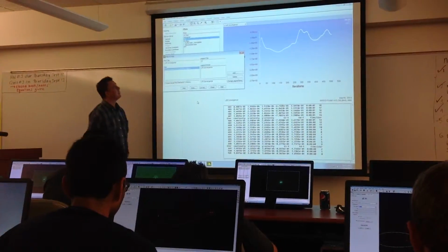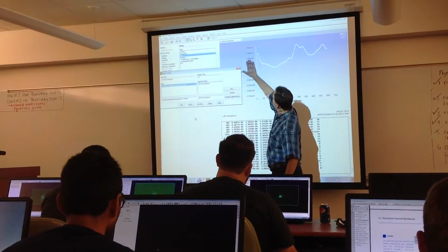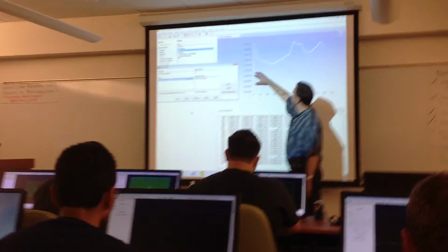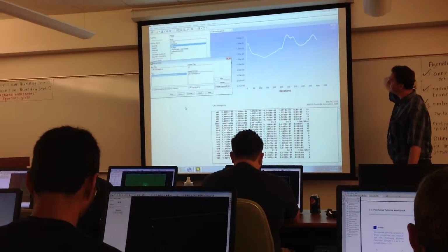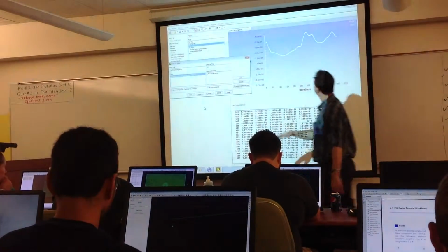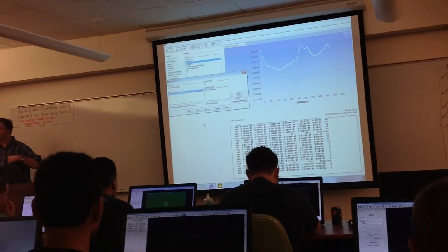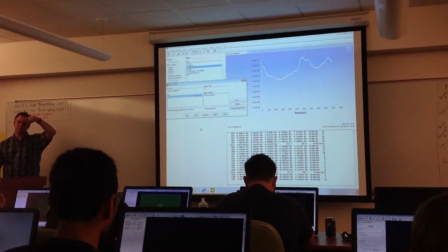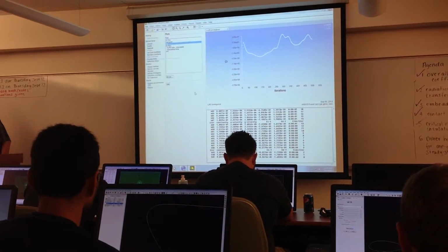Here's the lift coefficient history up here. So this is a lift coefficient of about -1 because I've got a downforce. Relative to 1, there's still some pretty strong variation. If you run long enough, you'll see a repeatable behavior, and that's the best you can do.